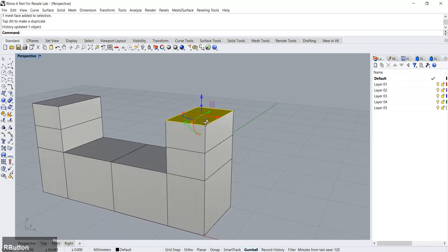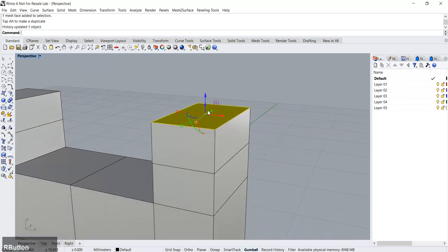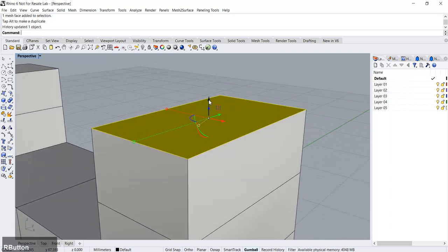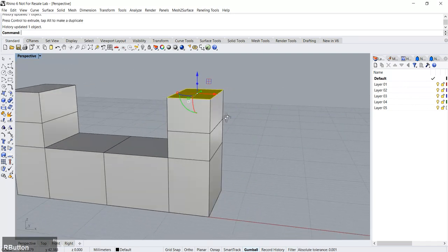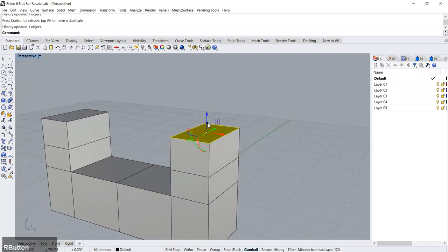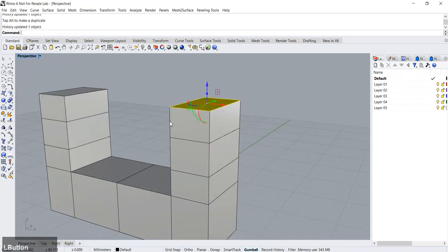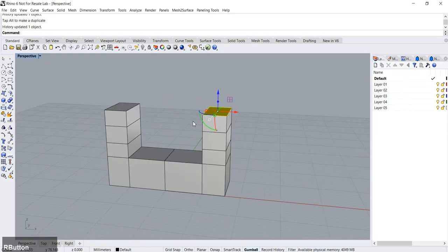Okay, what if I only want to move the face without doing extrusion? To do that, do not click on the dot, just click on the arrow itself. Okay, I want to extrude another region. So click this. The next thing I want to build is actually a bridge across here.